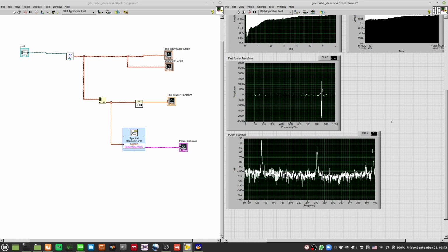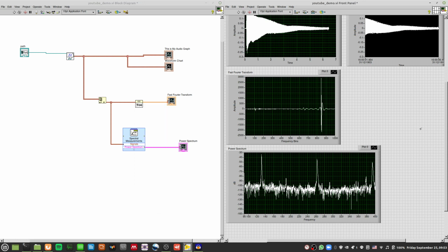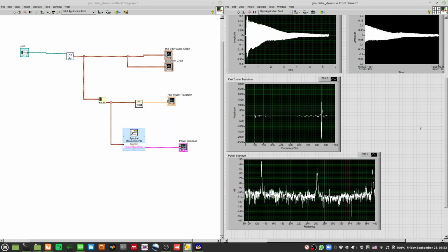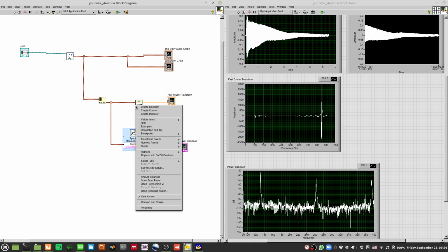But you see the C note is not 850 hertz. So this is around the frequency bin 850. So what's the deal with that? How then could you make these frequency bins at the bottom correspond to actual hertz? That's something we want to start talking about in this video. One clue I have for you is to set the FFT size to 44100, and you'll see some magic that actually occurs.